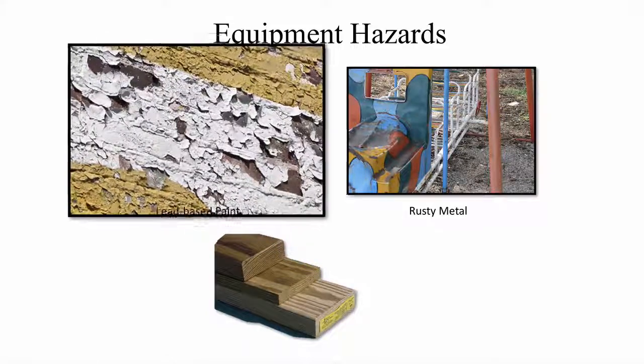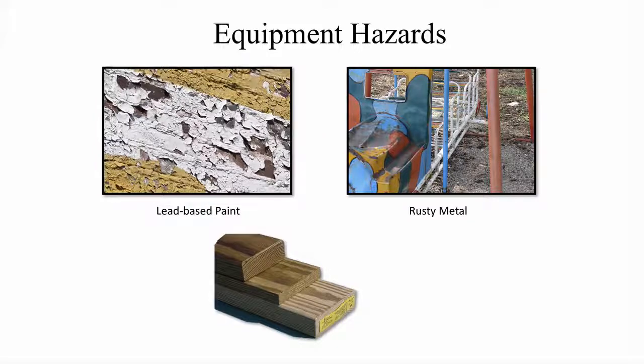Wood. There are still many playgrounds that are built using wood. Years ago, wood was treated using a form of arsenic to help prevent fungi, termites, and other insects. Now, wood treatment industries use two wood preservatives as a substitute for CCA pressure-treated lumber. This includes alkaline copper quat type C and copper azole type B. These new generations of preservatives are designed to perform and handle the same as CCA pressure-treated lumber with no risk.